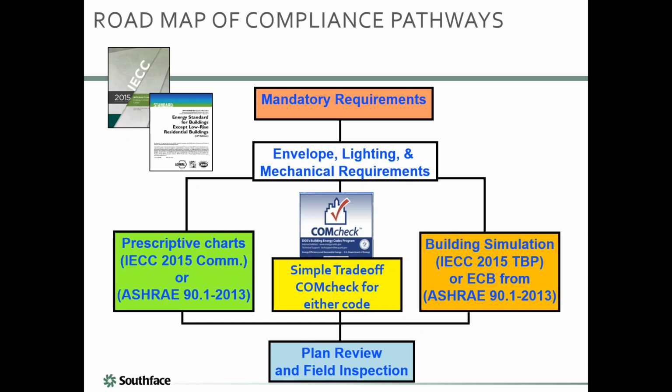So maybe your glazing is not quite meeting code, but you put extra insulation in the roof or whatever. But that's a great tool for showing that. And again, ComCheck does a really good job of not making you do as much math, and it provides a really nice printout and kind of a paper trail for the code department.